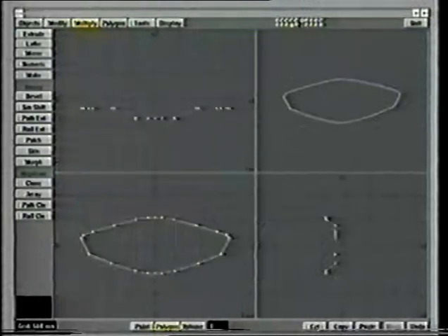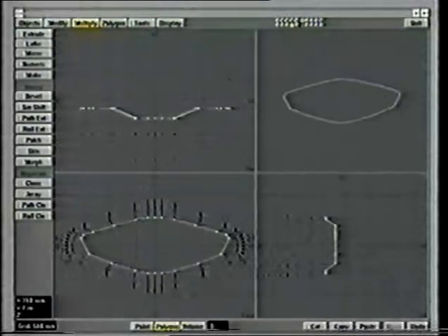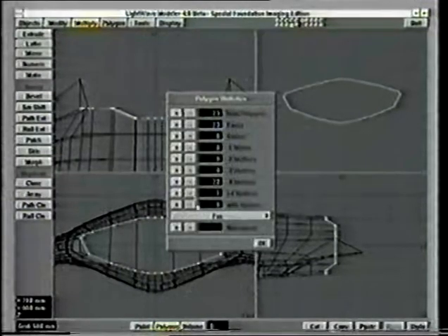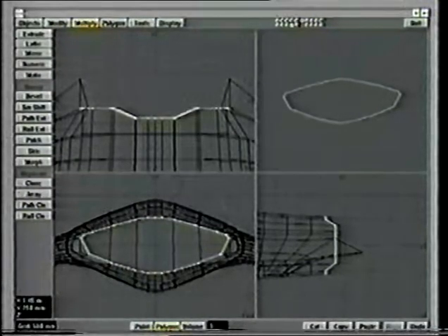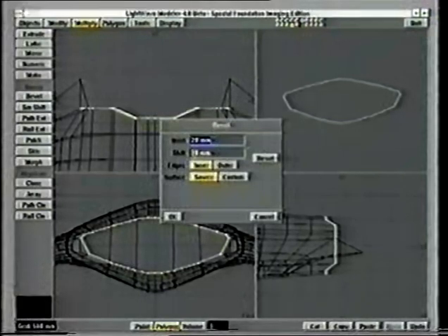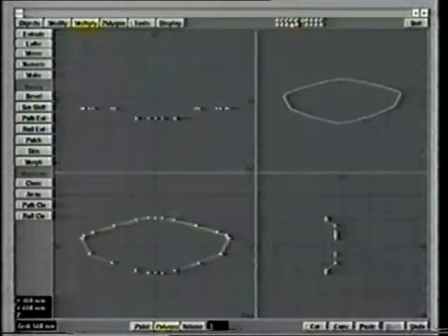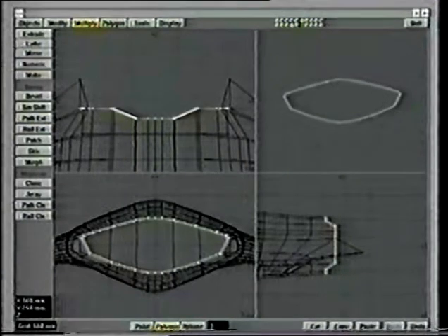Okay, cut the polygon, paste it back in, W key, select the one which has more than 4 vertices, and bevel again. Only this time let's do the shift of -20. Okay, that's there.